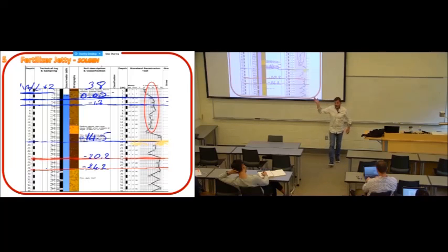So if SPT is 30, divide by 10, you can put 30 tons per square foot. That's a pretty good soil, safely, with about half-inch settlement expected. On the surface, if you go deeper, it's better.